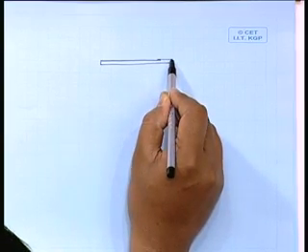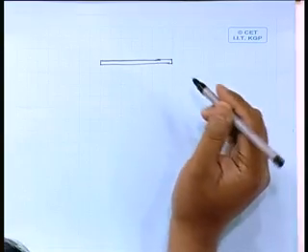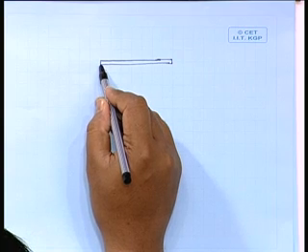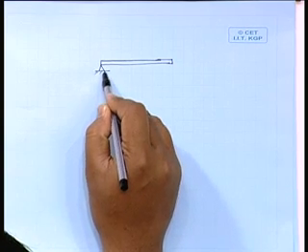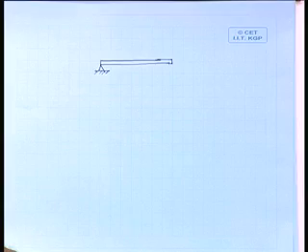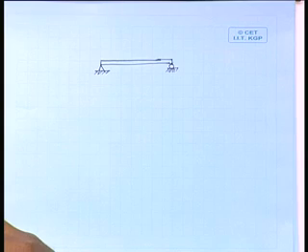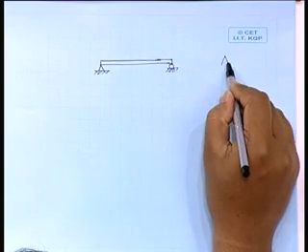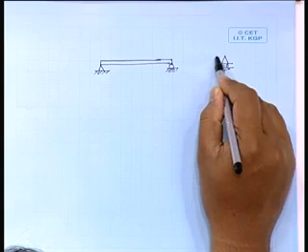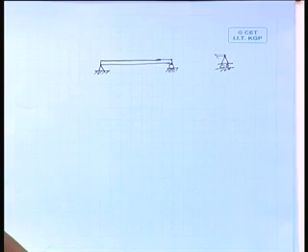Say there is a beam here and a hinge. Normally we try to put it in that manner. We will not show the pin and the plate, how it is connected with the support. So, in a convenient way, we just put a triangle, some line, something, to indicate it is a hinge. And for a roller, sometimes we just put a circle like that, or sometimes we put some roller like this, that is also another way.